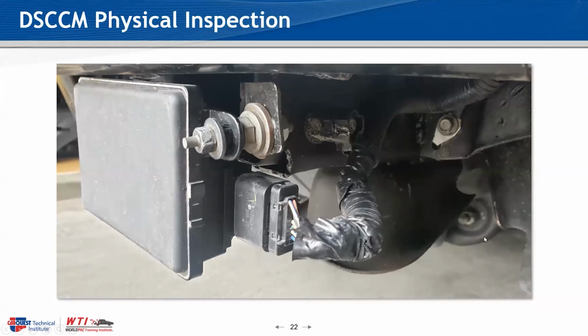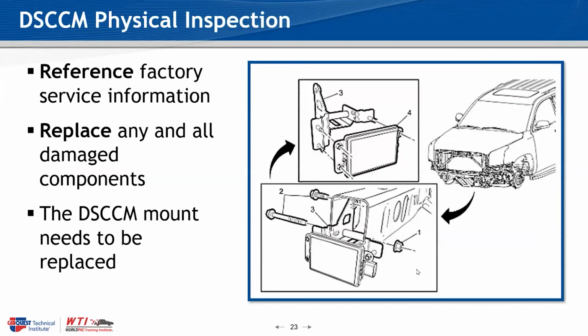It's bad. So at this point, I said, well, what is this supposed to look like? Was really my question. So we pulled some service information pictures, and looking at them, there's the mount that inserts into the end of the frame, and then 2 bolts that hold it, and then the radar bolts on the front there. Looking at it, I decided that this is probably not right. And doing some measurements and looking pretty closely, I actually determined that this vehicle needed a front frame section.